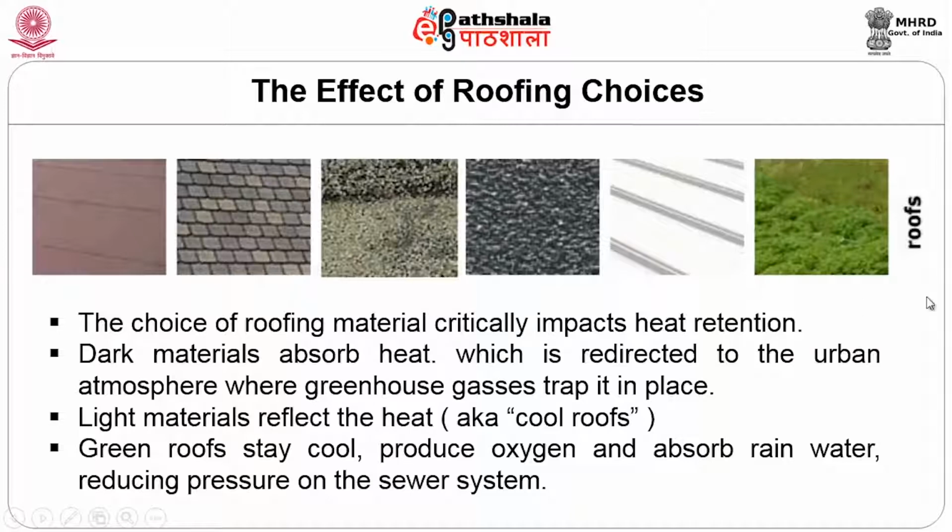So you can see that the green roof is most preferable, but care has to be taken when constructing a green roof. It has to be done in a way that does not encourage water retention or water seepage, so that there will be no dampness or patches seen inside the building. The quality of construction should be suitable to the method of the roofing choice we are choosing.